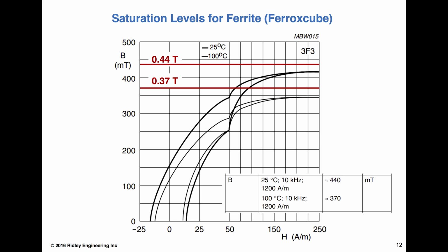Okay, comment here, obviously from a practicing engineer: what else would be dearly needed is tolerances on power losses and BSAT over production time, etc. Well, yeah, I would agree with that. That's kind of a little dark secret of the industry, that the core losses are strictly nominal. I have never seen a core manufacturer say, okay, we're going to guarantee your core loss is never going to be more than this. So I always feel bad for the guys in the aerospace industry who have to do their worst-case analysis, because when it comes to core loss, there is no worst-case analysis.